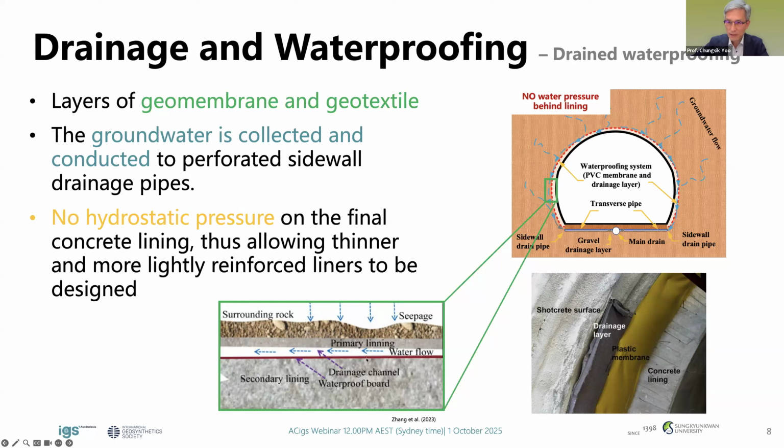So the critical advantage of this approach is that no hydrostatic pressure, which is water pressure, is exerted on the final concrete lining. So we can discard the water pressure for design. That means this significantly reduces the structural demand on the lining, meaning it can be designed to be thinner and more lightly reinforced.